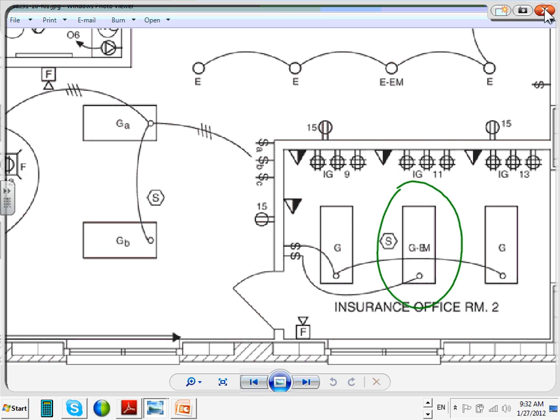Then you can switch the fixture on and off, no problem. But if the power goes off in the area, there's a little relay inside the fixture that switches you to the battery, only if the circuit breaker trips. If you turn the light off, it wouldn't turn on again. Only if the circuit breaker trips.